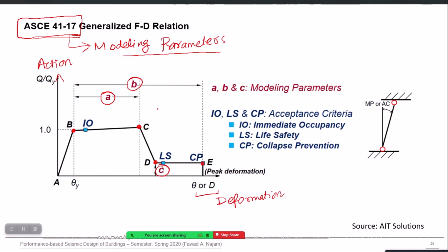So for example, if I want to model a reinforced concrete beam using the moment hinge, ASCE 41 will give me how much rotation there will be in my beam from B to C and from B to the last point, based on what reinforcement I have, what cross section size, what f'c, what Fy, for example.